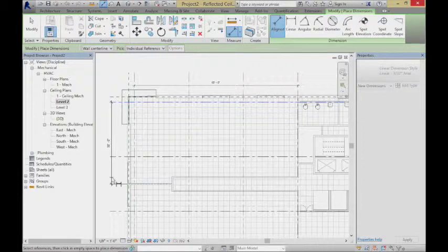That sounds so little. Okay, how about 960 would be the minimum? That's 4 air changes. Let's say I'm going to up it a little bit, to 1980, which would be 8 air changes, so sort of higher. Now I probably won't actually have something that'll get me to that right away. If I'm using 500 per terminal, I'd use 4 of them. So again, there's this flexibility in terms of the number of air changes.